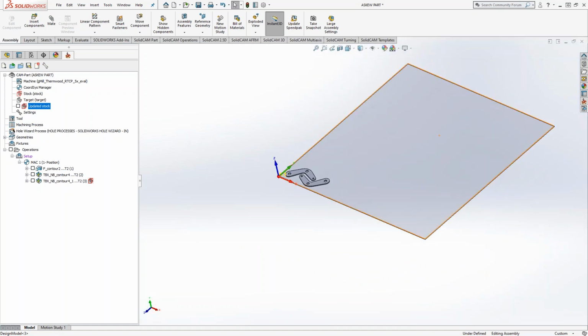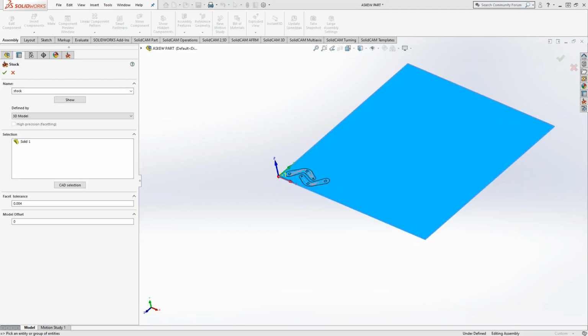The 3D model is still the 5 foot by 5 foot, 1/4 inch thick sheet. But since we're going to be talking about stock today, I thought I would show you how you could do something similar. Basically, you could do this same sort of shape using the box definition in your stock manager. But if you do it as a 3D model, then it becomes associative as well. It adds a level of associativity to your part.